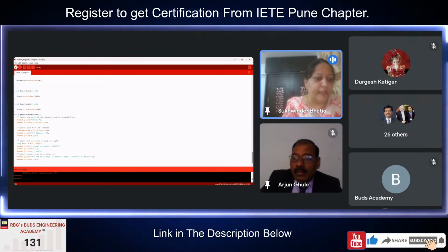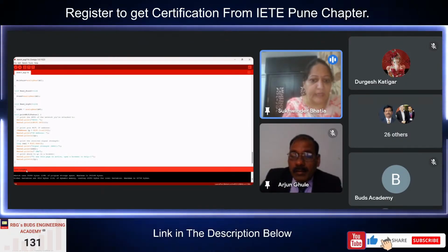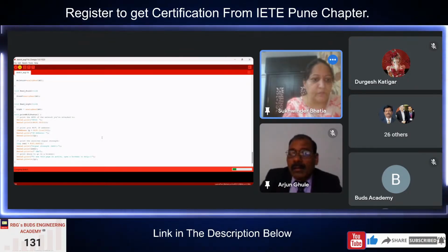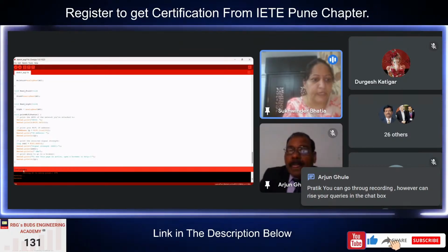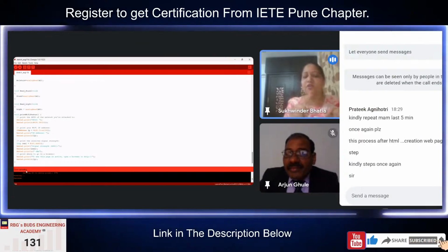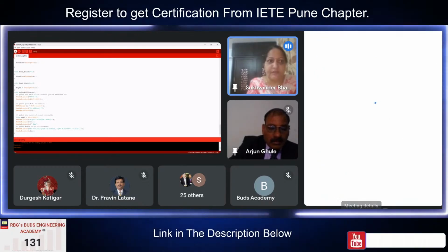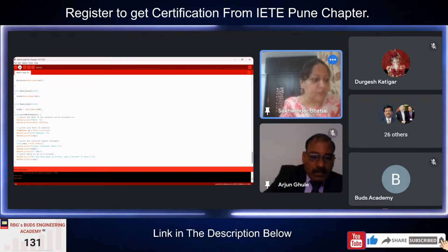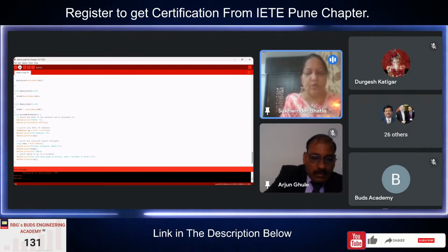So once it is done, we'll verify the program. So you can see here compiling sketch at the bottom on this particular red line. It is compiling. So done with the compiling. And then we'll say upload the code. So it is uploading right now and done uploading. So these are similar ways for those of you who have used Arduino. Same steps are there over there also. We need to first verify and then we need to upload. Once it is compiled, then we need to upload the code. So that means that my code has been actually uploaded onto my board.